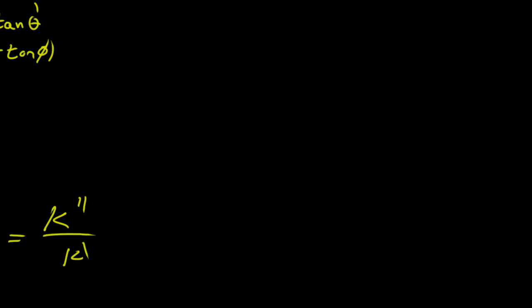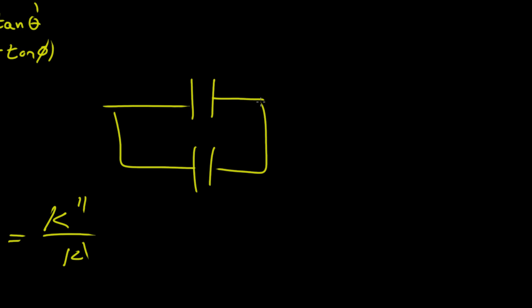You could also draw your equivalent circuit that we used earlier to describe the different parameters. We drew the top as a motional branch. So the losses occurring in that branch would have to do with the complex value of the elastic compliance, and similarly the bottom, their losses would have to do with the complex value of the permittivity under constant strain.